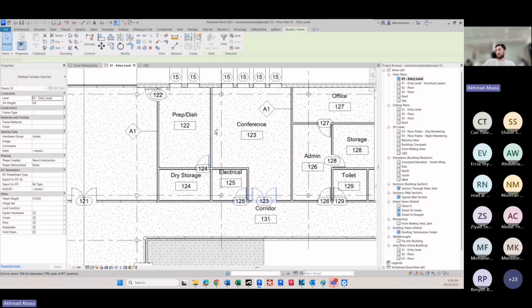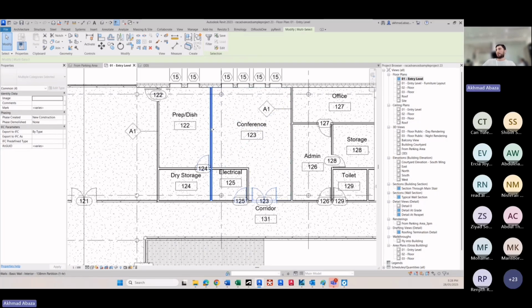I will add to my selection also these walls. Now we will see that under our selection, there are a lot of items that do not belong to the same category. This is just to confirm that the category concept is very important in Revit. That's why the category you cannot modify, the category you cannot add or move.